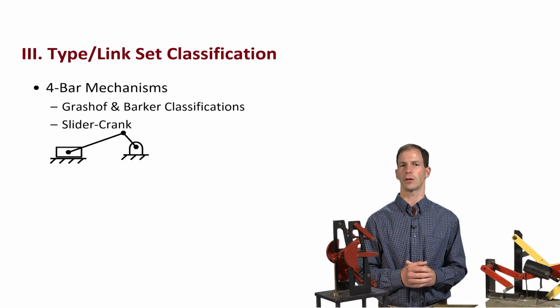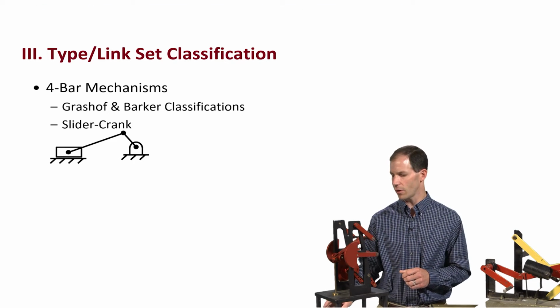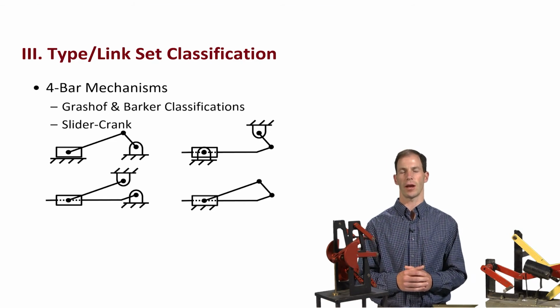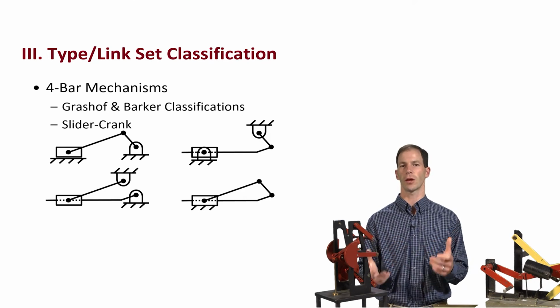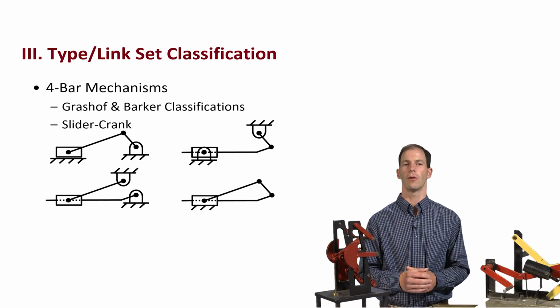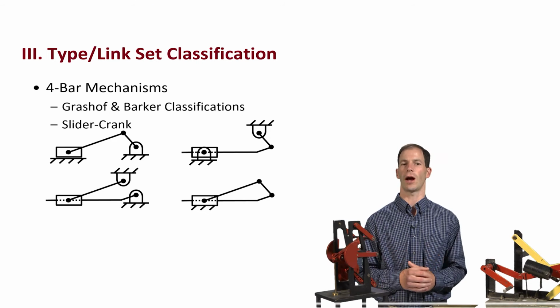This is the common kinematic inversion, but recognize that I can create 3 other kinematic inversions of these as well, tumbling block, turning block mechanisms, which are simply changing what is ground in this mechanism.